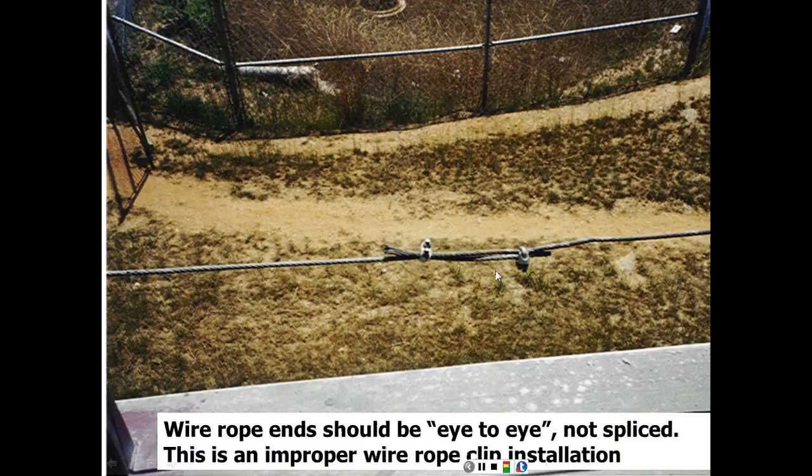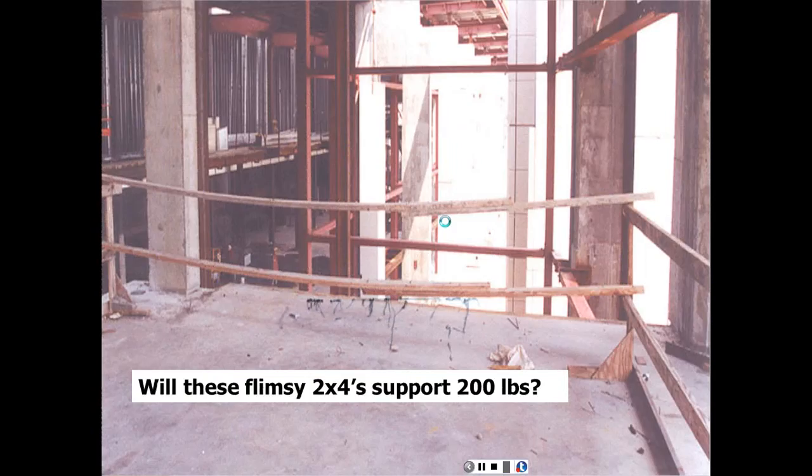This one has splicing, so that is not going to work well, because this is going to be a weakness point. It's not strong enough. Most likely it's going to deflect more than 3 inches. Obviously this is not a proper guardrail. It's deflecting under its own weight, so it's not strong enough to resist the 200 pounds.